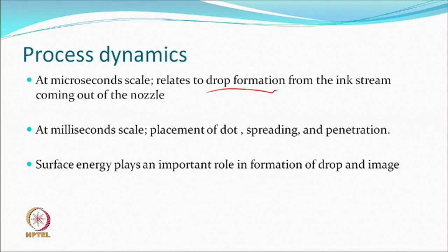The surface energy of the solution itself, which is related to surface tension, can be changed by adding surface active agents or any other solvent that you add. Like when you dilute something, viscosity changes, we understand, but if you add instead of the same solvent another solvent, then the energy also changes, other than the viscosity, and can play a role in formation of a drop and an image.